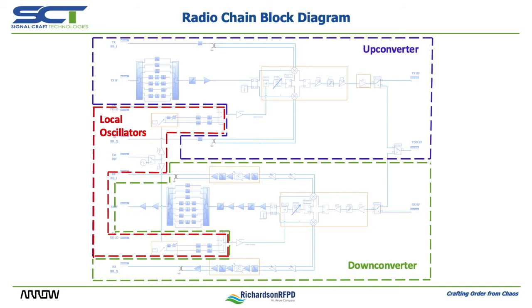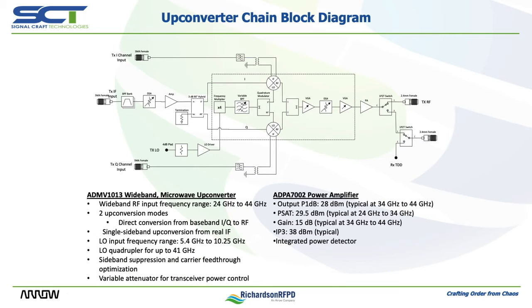On the left, we can see the shared frequency reference and the 2 internal oscillators. On the far right of the diagram, you may note the connectivity between the up and down converter paths required to support TDD functionality. This diagram represents a simplified view of the up converter block, also known as the transmit chain in RadioThorium. Key blocks implemented with the help of Analog Devices semiconductors are shown here for reference.